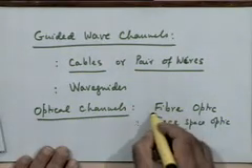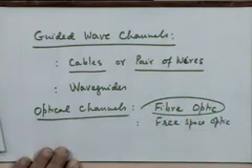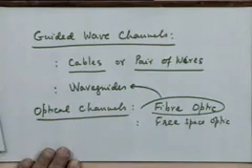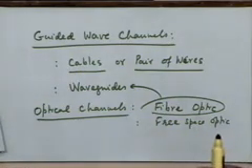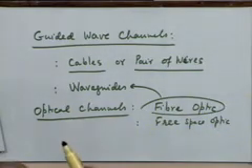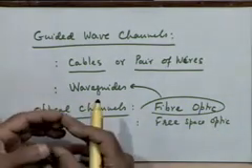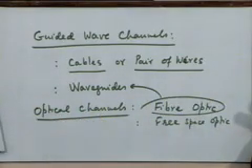But really speaking, the fiber optic communication is the same thing as a waveguide. If you look at it, it's a cylindrical waveguide in which it so happens that the cylinder is very thin, right? And you are transmitting light energy through it, which is also electromagnetic energy. The actual propagation mechanisms are exactly the same, right? So they can be treated like that.